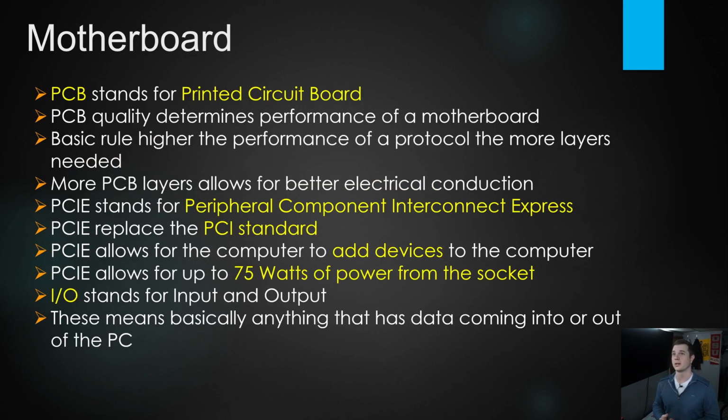PCB stands for Printed Circuit Board. PCB quality determines the performance of the motherboard mostly through signal integrity, and the better signal integrity that you need, the more PCB layers that you also need as well. That's part of the reason why motherboard cost has gone up, particularly on the enthusiast consumer side, significantly over the last few years. That's obviously not the only factor, but it is a significant one nonetheless.